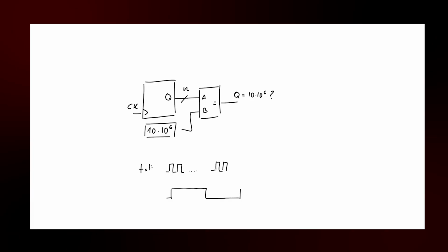By the way, I'm supposing for the sake of simplicity that the 1 Hz signal has to have 50% duty cycle. This means that it spends 50% of its period in a high state and 50% in a low state. Easy enough, I guess you can probably see that we need to count for half these 10 million pulses before toggling the signal. Half of 10 million is 5 million. If we flip a bit every 5 million pulses of the OCXO signal, we'll have a 1 Hz signal.